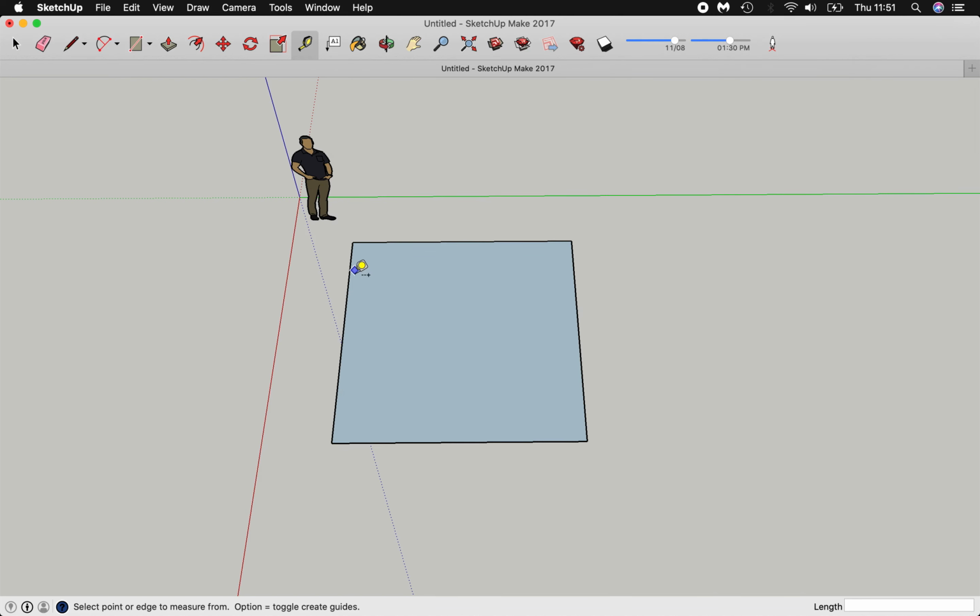Click on it and click one side. As you can see, a dotted line appears and then a number that corresponds to the length. If we look in the right hand corner, we also have a length appear in centimetres. If we double click on that and on our keypad type in 200 for example, it will move the line from its original orientation.